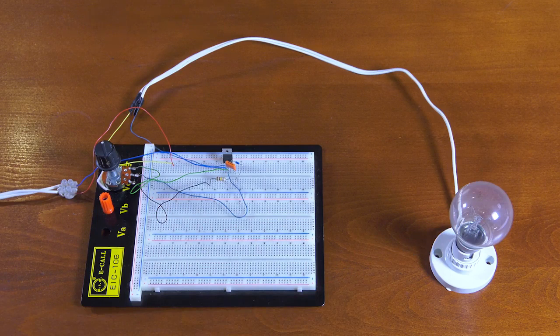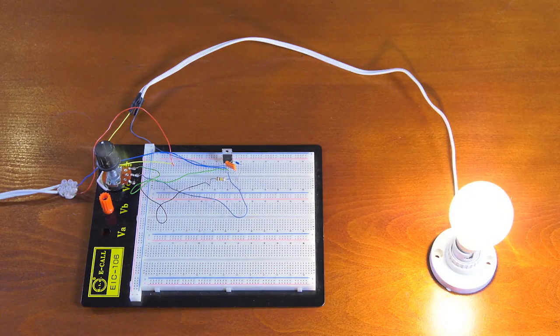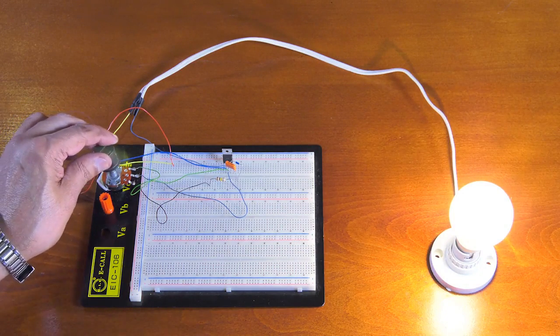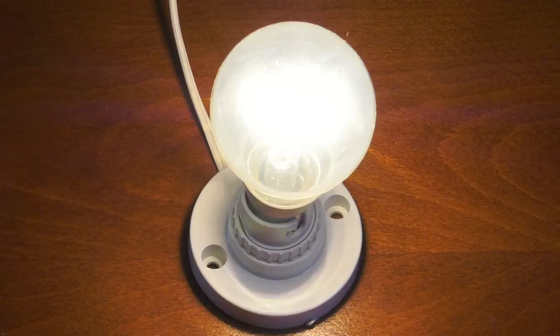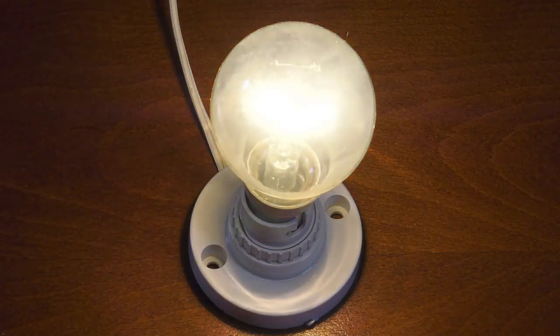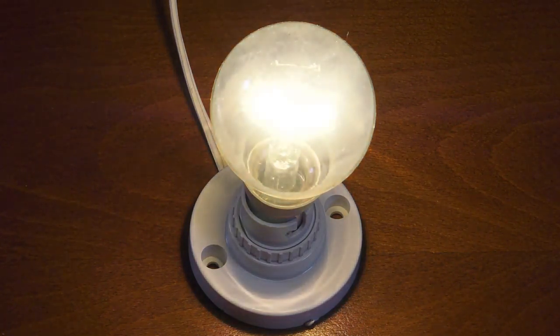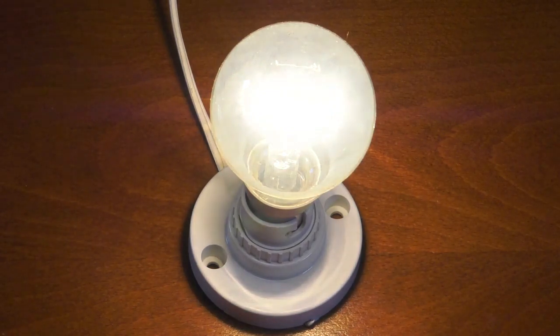In fact, you can use it for any AC application where you wish to vary the AC potential to the load. So we are now going to demonstrate how the circuit works by using an incandescent lamp, and you'll see how the potential at the light bulb changes like so. So if you had a motor where the lamp is, you'd alter the speed of that motor accordingly. So the triac is a very useful component. In fact, it is used for all AC drives in industry. A very, very popular component.